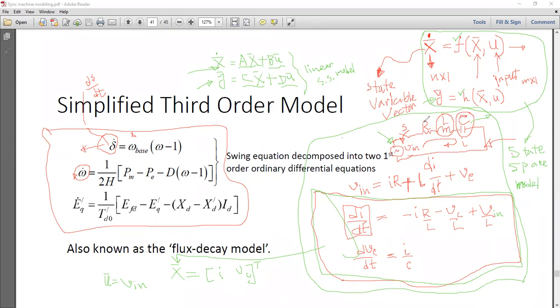It could be the voltage across the resistor, or you might want to just record the value. Whichever value you want to record out of this network, you can choose it as your Y. So is it voltage across resistor and inductor? It's up to you. You can choose 2, you can choose 3, you can choose all the voltages. I want to measure all of these 3 voltages.